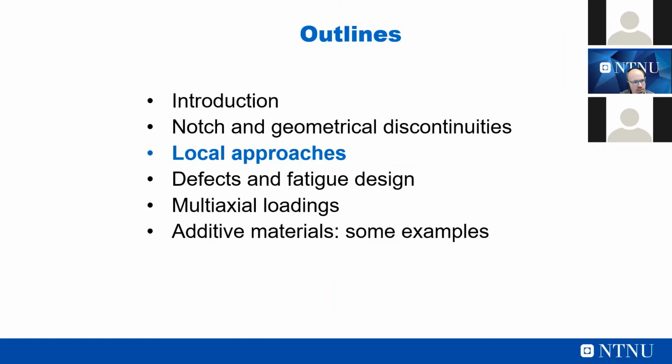But what I want to mention is that if you want to design for additive manufacturing, you have to face complexity in your components, and so you have to at least understand what is a notch, what is a geometrical discontinuity, what is a point-based approach, and what is a stress field-based approach. Because if you have a sharp notch, you have to consider a notch stress intensity factor parameter. If you have a blunt notch, you have to consider a point method. But in any case, you have to be able to consider a notch properly and to consider the stress distribution ahead of the notch. The complexity that we can achieve with additive manufacturing is good, but at the same time is creating a lot of problems because we have complexity in geometry.